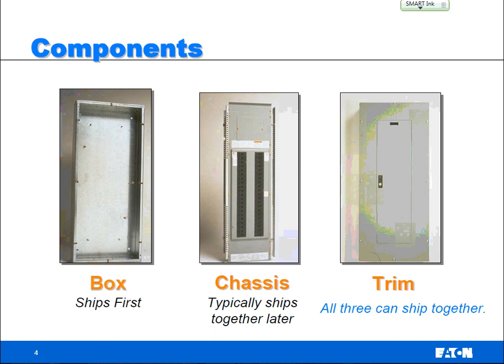So in addition to, say, 1.5 inches of air, you've also got some extra protection here. The more insulation in here, the smaller the equipment goes. You can see as you start designing things, you're going to get a trade-off. Everybody's going to want it smaller. The architect's going to say, I'm giving you a smaller room. That's almost every project. And the field installing contractor is going to pull you the opposite direction. They're going to say, make things a little bigger so I can get my hands in here and do some work. As a designer, you're going to have that trade-off of optimizing space for the architect and a good product for the contractor.